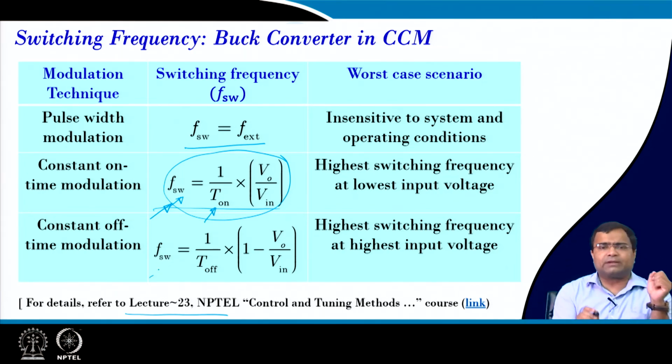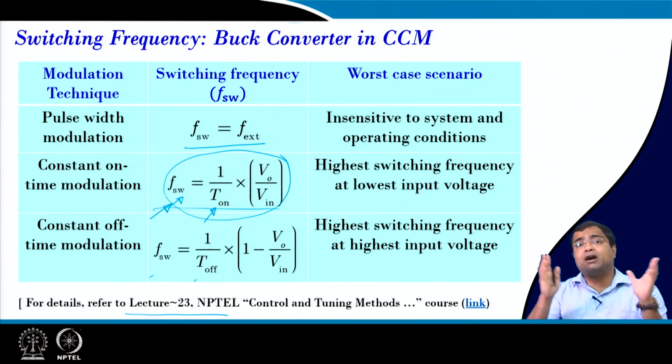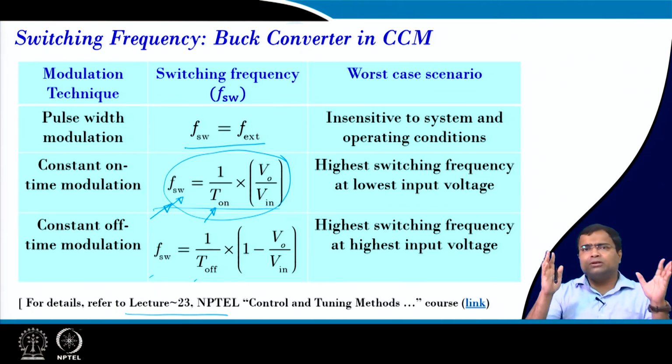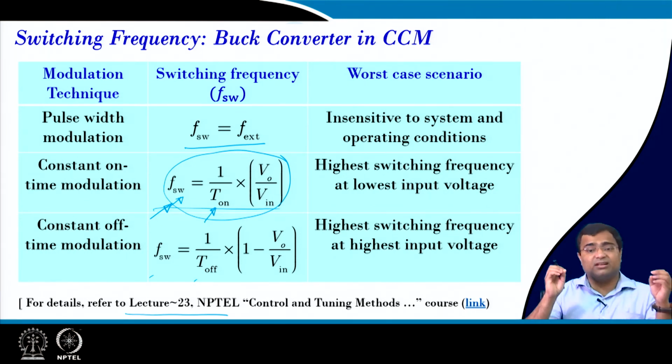Similarly, for constant off time we can adjust the off time. But once we go to digital control, I will show you such mechanisms are very simple, because you have a digital counter and you can use a time to digital converter just to lock the frequency, maybe very fast in fact, and without additional resources like in analog control. In a digital platform we will have a counter, so we can very effectively adjust the switching frequency.